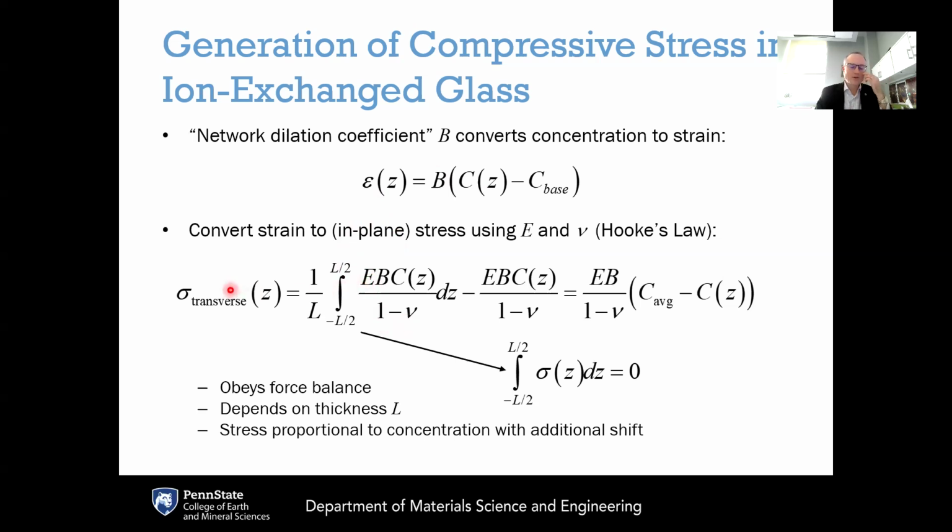And all of this needs to be normalized such that the integral of the stress across the entire thickness ends up being 0. This means that all of the compressive stress is balanced by all of the tensile stress. So this entire integral here must go to 0. This is the so-called force balance condition. So all of the forces acting in the compressive manner are balanced by the forces acting in the tensile manner. And so integrating the stress profile across the full thickness gives 0. And the equation then that this gives is that